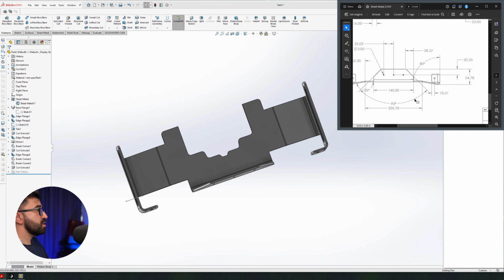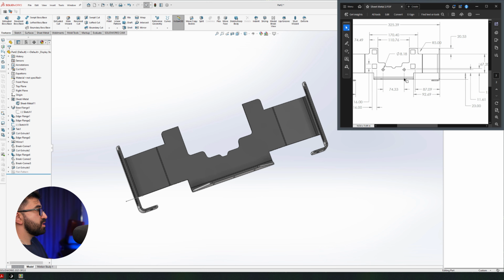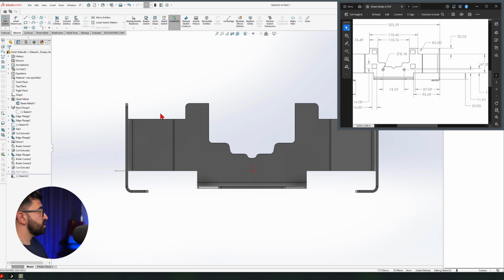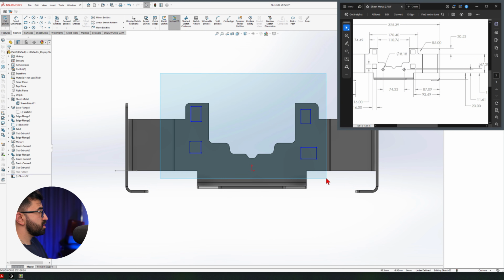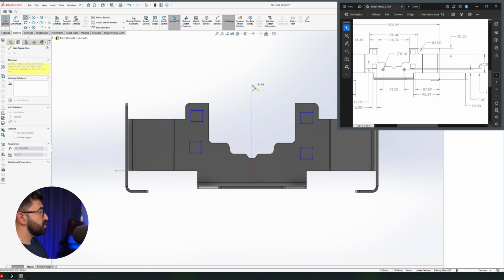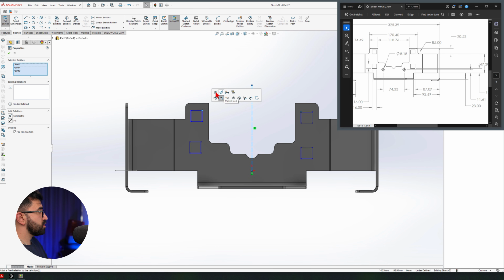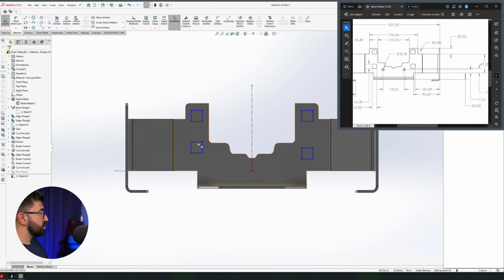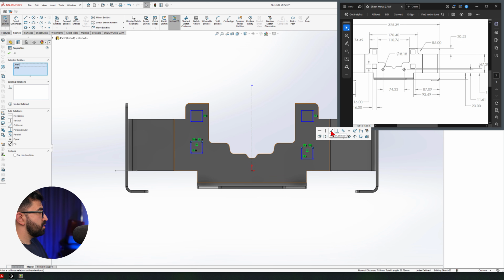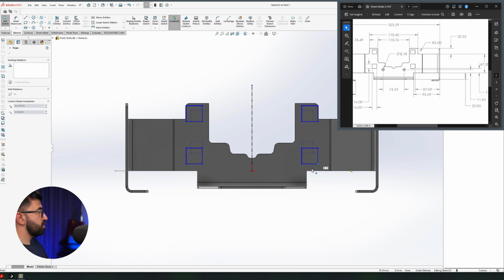Still some stuff missing. These 4 rectangles and 2 holes, which I just do here. Quickly, 4 rectangles. The faster way would be to select them all, have them equal. No, there are 4 equal rectangles. A center line vertically up for symmetry, and this point line and this point symmetrical. This line and this line in a collinear relationship. This line and this line the same, this line and this line the same, as well as this line and this line the same. Now if I move one of them, all of them will move.